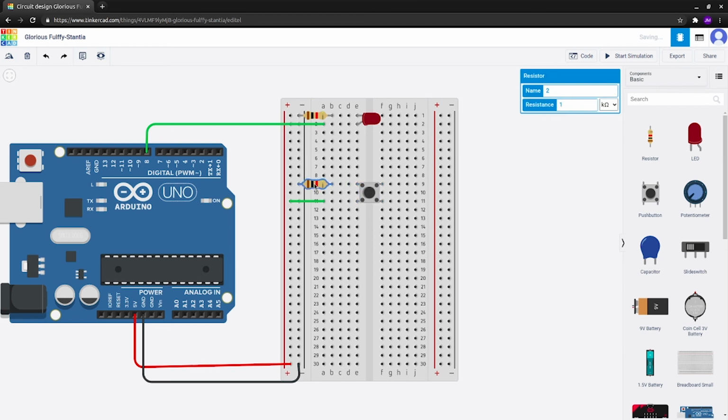So we use a resistor for the connection to ground so that when the button is pressed, the voltage will drop across the resistor. This is so that there isn't a direct connection from the power rail to ground, as this can be dangerous and is a short circuit. Now let's pick our input pin to be 5 and connect it between the resistor and the button.